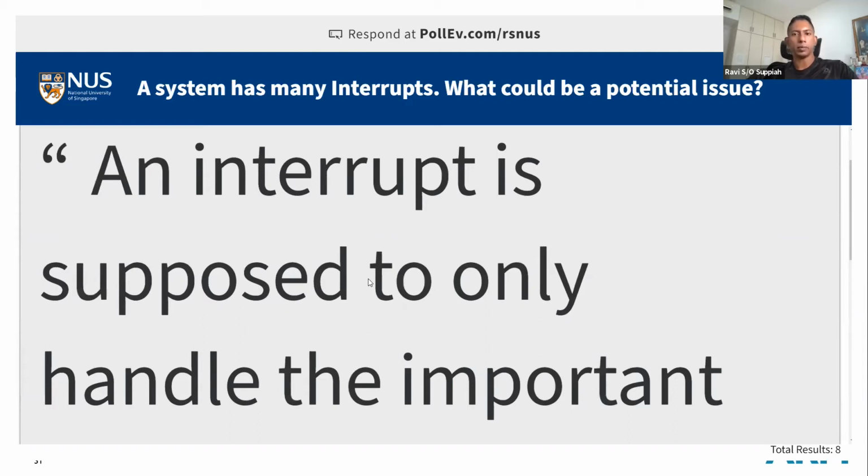All right, I think we talked about nested interrupts before in EPP2, where you can have an interrupt being interrupted by another peripheral of higher priority. These are usually configurable. It's whether you want to allow it or not allow it in the system. As you can see, an interrupt-based foreground background system is very useful, but it also comes with its own share of challenges.